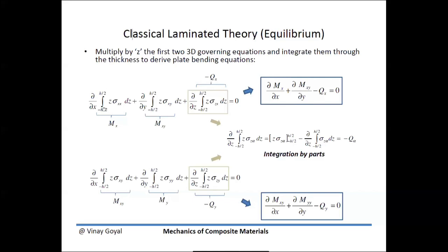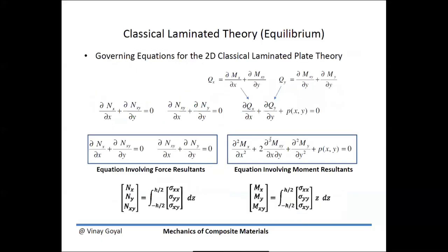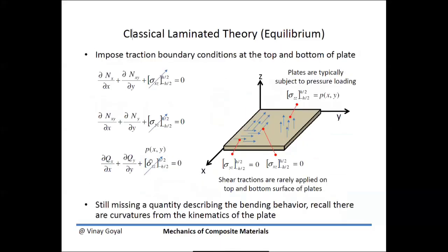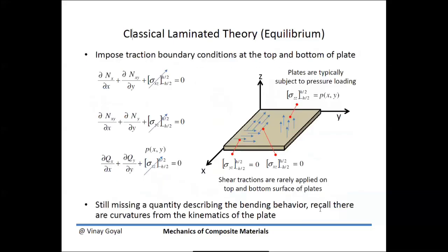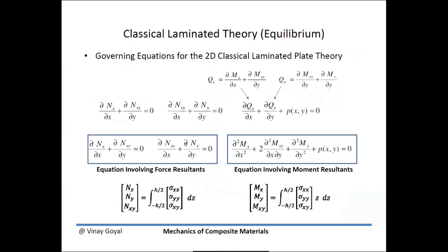And I want you to focus on the moments. These are moments, and they have units of force somehow, but these are important quantities: the bending moments that resist the external loading conditions. So I can now plug these two equations into the third equation. I can plug qx and qy into this equation, and what I will find is a governing equation governing the moment resultants. So this plugs into here, and I get the moment resultant governing equation.